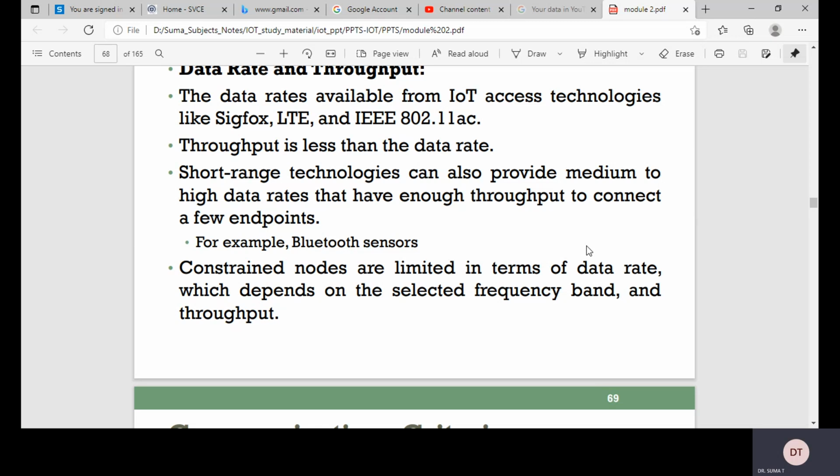Polling impacts the design because all devices share the constrained bandwidth capacity. A discussion of data rate and bandwidth on lossy networks must look at the real throughput, or throughput seen by the application. While it may be less important for constrained nodes that send only one message a day, real throughput is often very important for constrained devices implementing an IP stack. Throughput is a lower percentage of the data rate even if the node gets the full constrained network in a